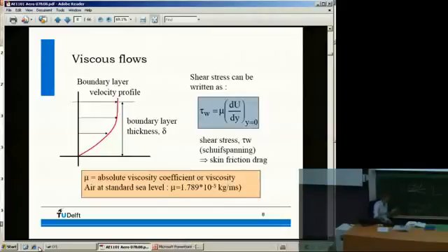Okay, so this here is a bit confusing because of the reality and how you normally plot it. Here we have our surface, our plate. We have a boundary layer over it. So 0 velocity here, and the velocity is increasing. This is the distance to the surface. If I blow air over this table, slightly above I have some velocity, some velocity here, some velocity here.